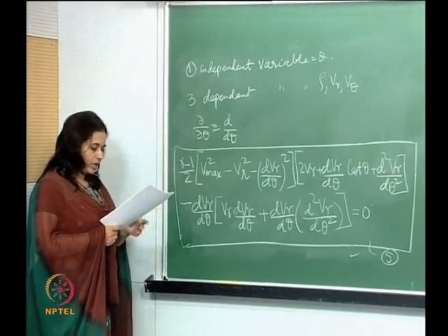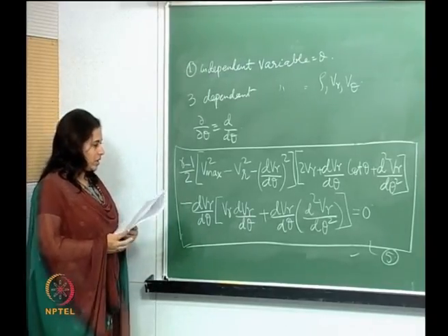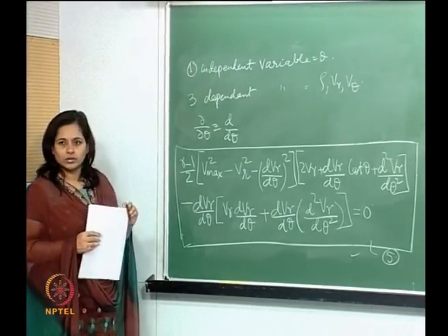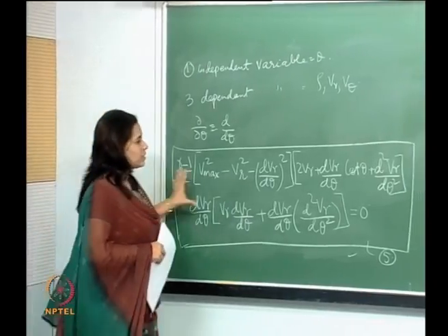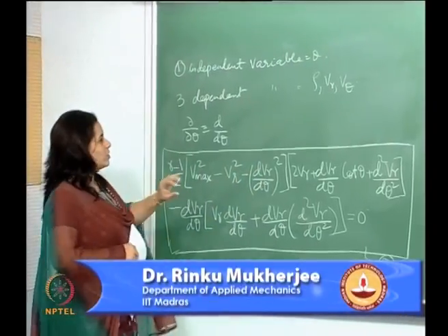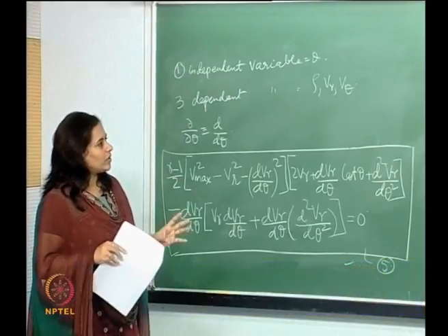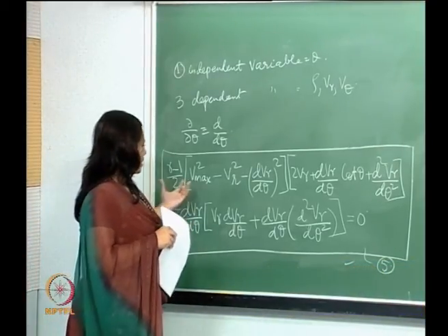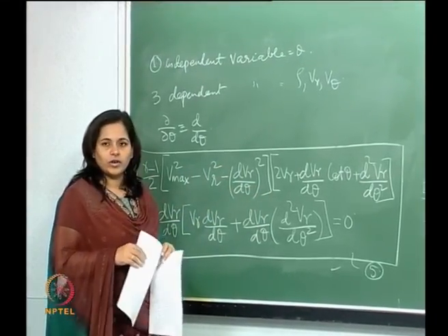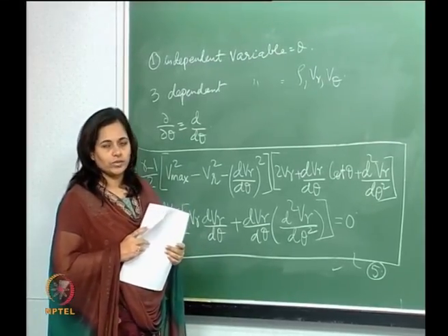Okay, let's stop here. Of course, there is no closed form solution for this. We have to solve this numerically. We will see how. So, essentially, now at least we have got an equation with which we can work. We have made no linearizations, no assumptions, nothing. We have just gone from basic governing equations for conical flow and got this nice expression, and we will see how we can solve this for the kind of flow that we talked about, which is conical axisymmetric flow. Okay. Thanks.